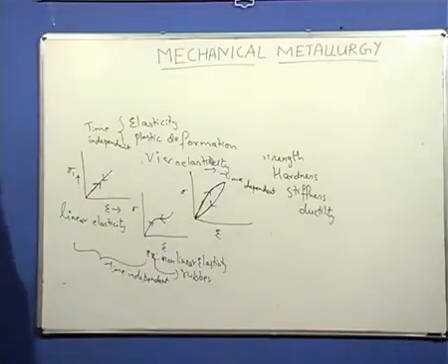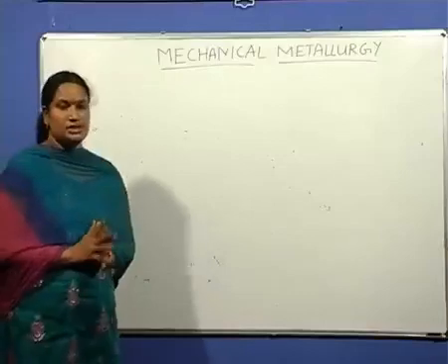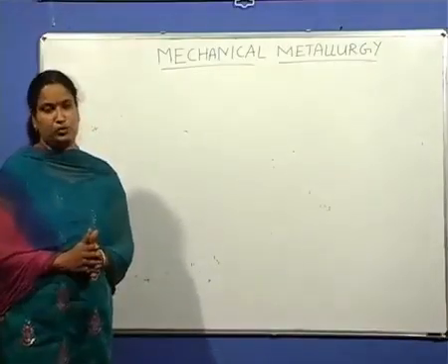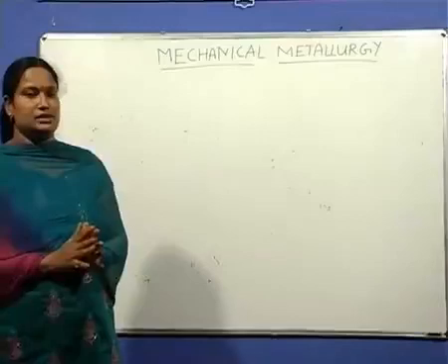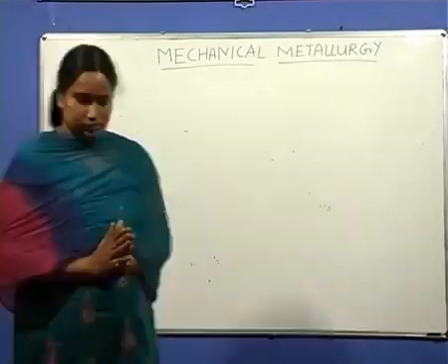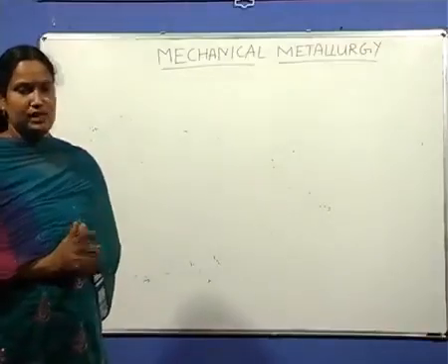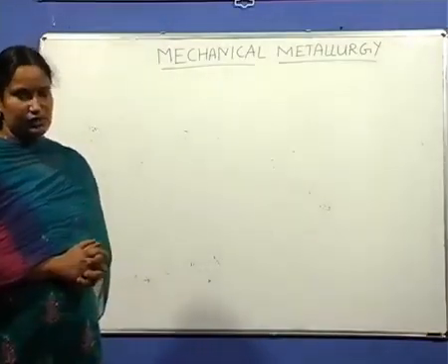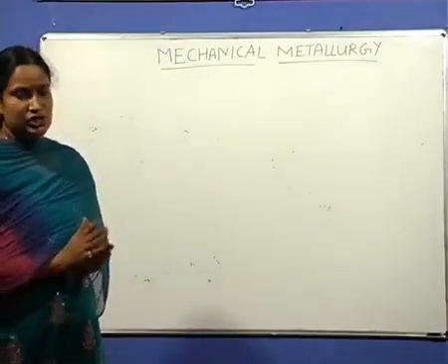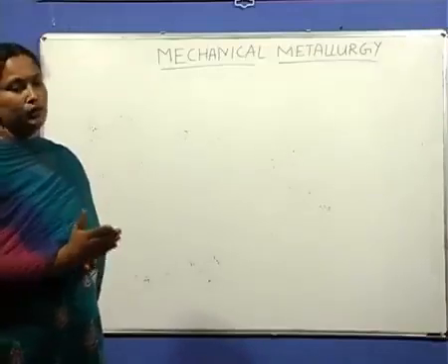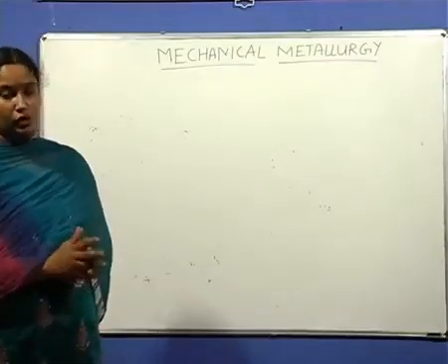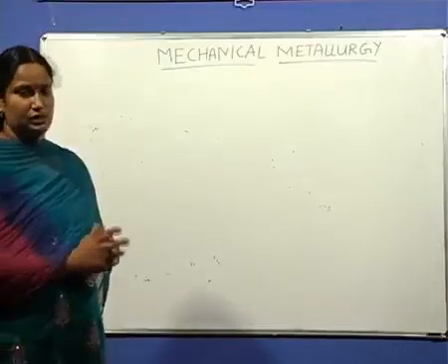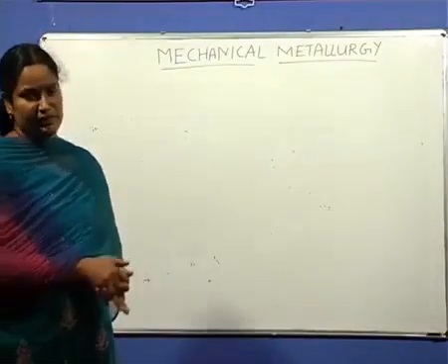So these are the three types of deformations which we have discussed: elastic, plastic, and viscoelastic. Linear elasticity is where the stress-strain curve follows the same path upon loading and unloading, and it is time independent elastic deformation. Non-linear elasticity has two types, that is time dependent as well as time independent.